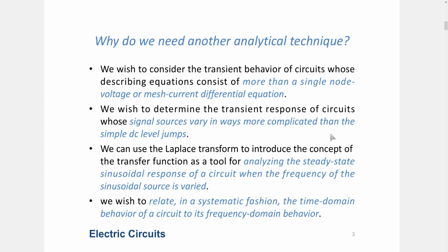We can use the Laplace transform to introduce the concept of the transfer function, which is very important in electrical engineering because it constitutes a new paradigm, a new perspective for engineers to handle complex system level problems. So we use this as a tool for analyzing the steady state sinusoidal response of a circuit when the frequency of the sinusoidal source is varying.